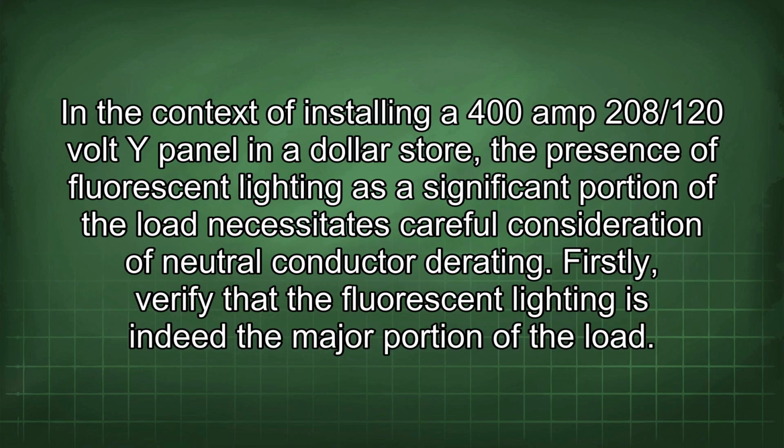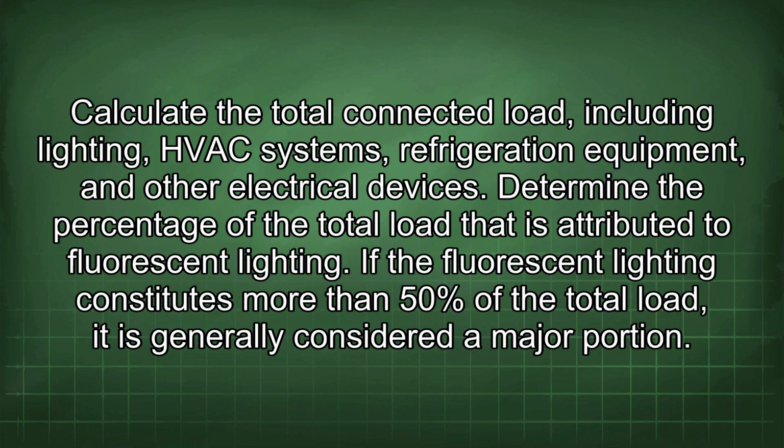In the context of installing a 400 amp 208/120 volt Y panel in a dollar store, the presence of fluorescent lighting as a significant portion of the load necessitates careful consideration of neutral conductor derating. Firstly, verify that the fluorescent lighting is indeed the major portion of the load. Calculate the total connected load, including lighting, HVAC systems, refrigeration equipment, and other electrical devices.